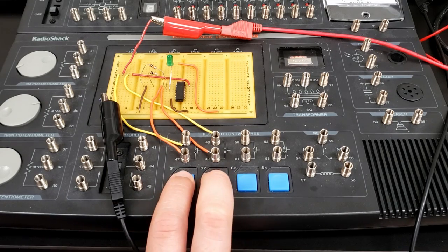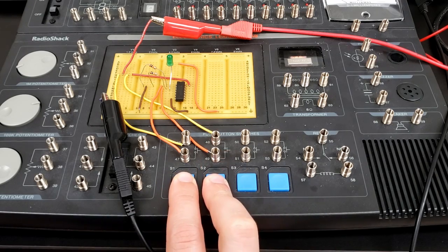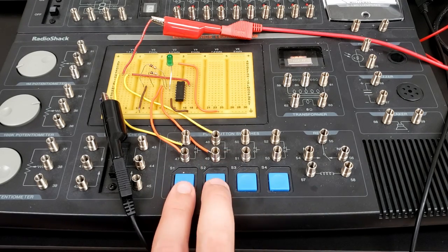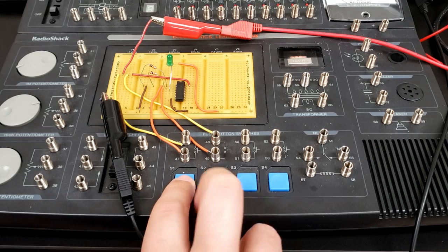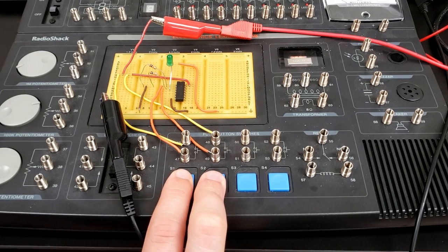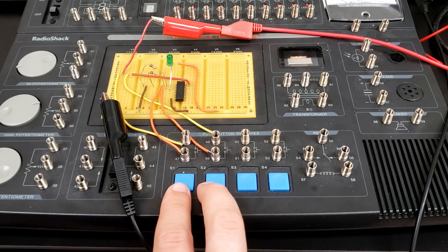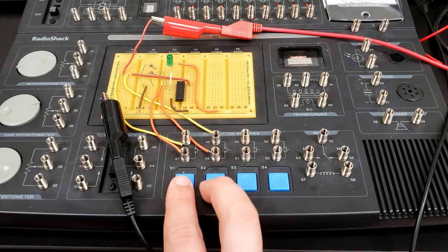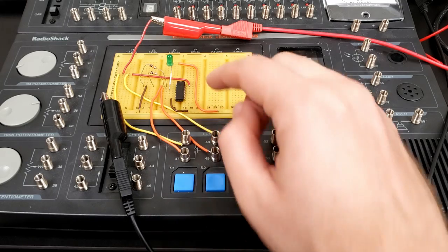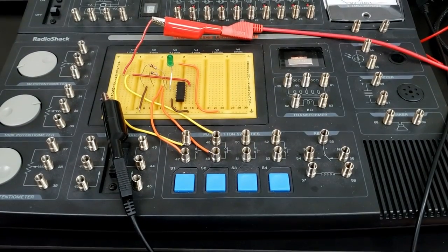And now if I hit both of them at the same time, I don't get any output. Okay, so I only have an output if I'm pressing either S1 or S2. If they're both off or if they're both on, I get no output. All right, so now you can again use that truth table. You can determine that truth table and then use it to find out what type of gate this 4070 is. All right, so that's going to be all of the labs.